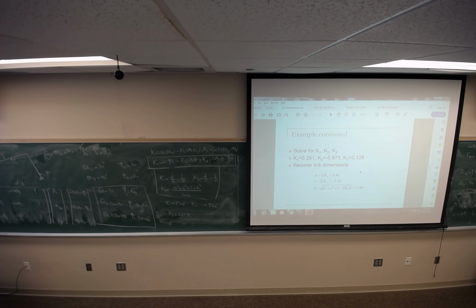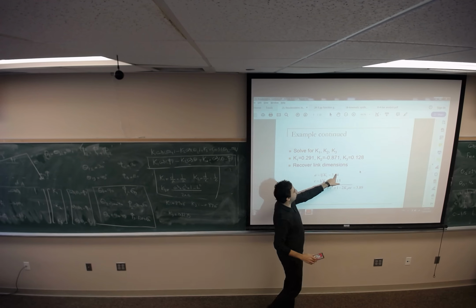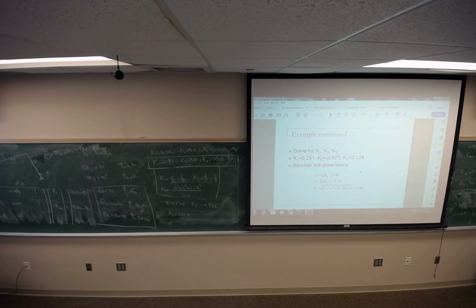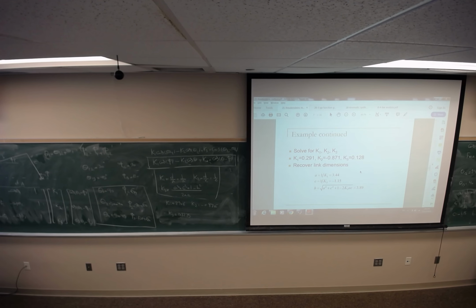Now, if you want to draw the mechanism at the first precision point, where A is 3.44, theta 1 is 40. At the angle of 40, go by 3.44. D is 1, so D is here, O2, O4.